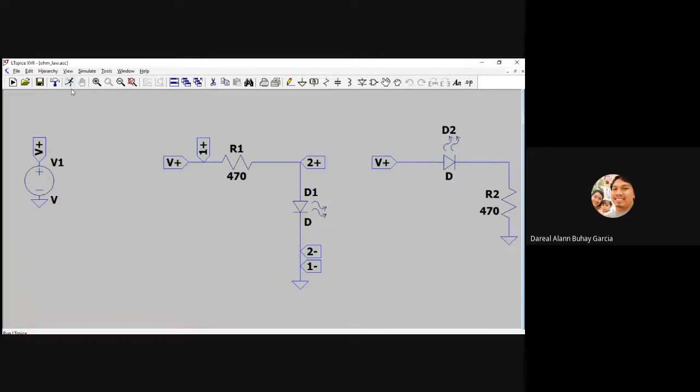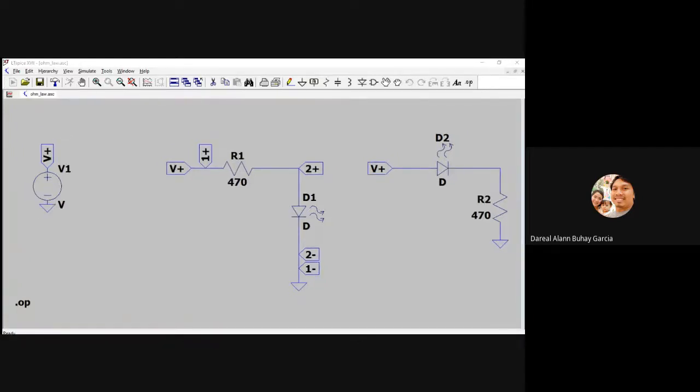So if we press the run button and press OK, it says no analysis requested found. So we click DC operating point and type here. Actually, the command is supposed to be .op, but you can just click the ribbons. Then, nothing came out, zero, none values.